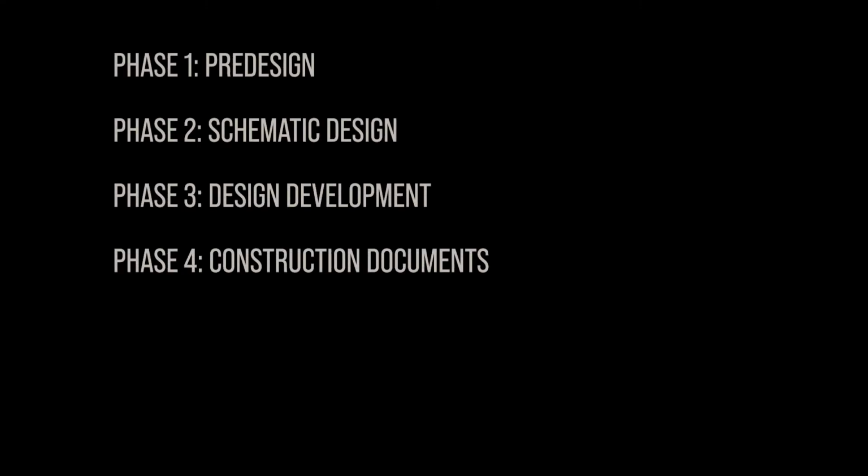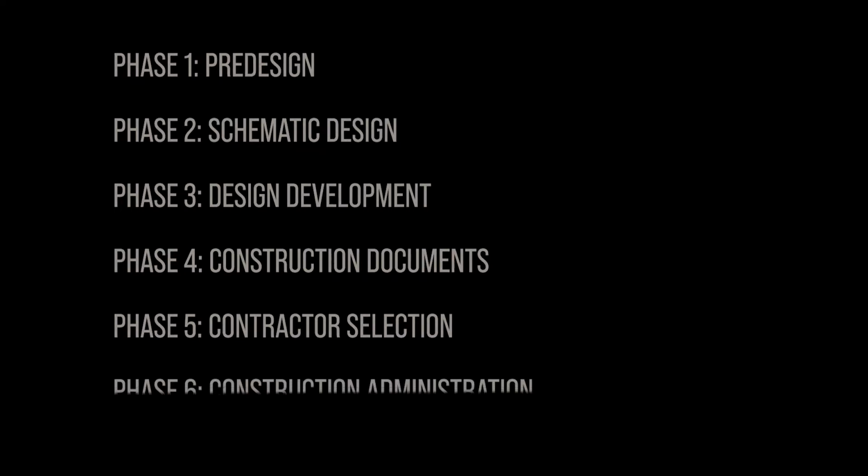At the end of the process, you'll have not only a thoughtfully designed project, but the shared experience of having collaboratively designed it. Architects, for the most part, follow a similar path to arrive at a finished project. There are 6 general phases to the design process: pre-design, schematic design, design development, construction documents, contractor selection, and construction administration. The phases are sequential and they build on the work completed and agreed to in each preceding phase.